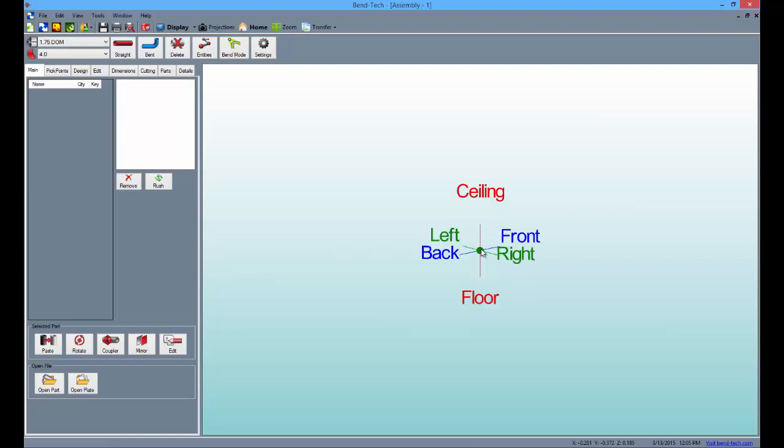First, spin the wheel on the mouse to cause the screen to zoom in and out. Spinning the wheel backwards to zoom in and forward to zoom out. Make sure that the cursor is placed over the part you're trying to see closer or further away. Otherwise, you could zoom the part right off the screen.